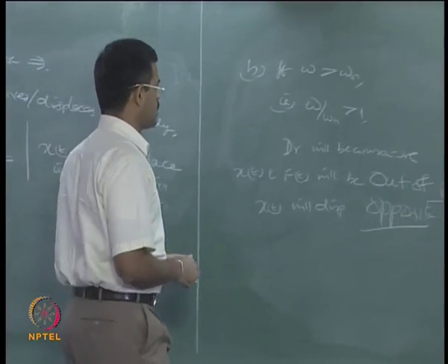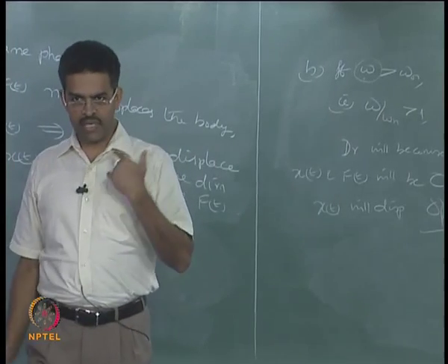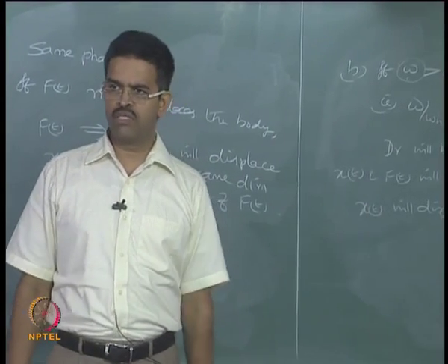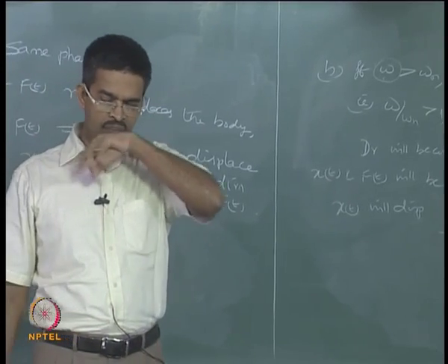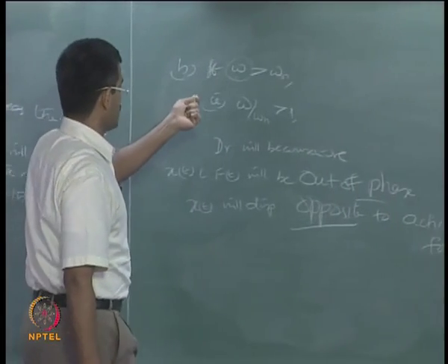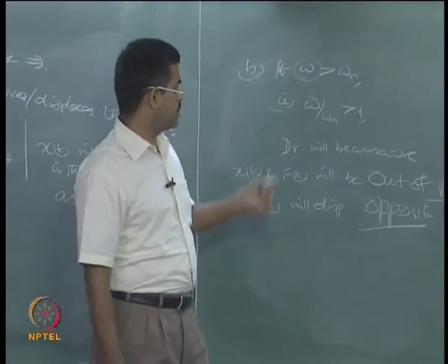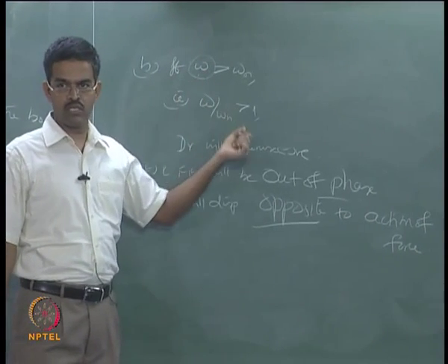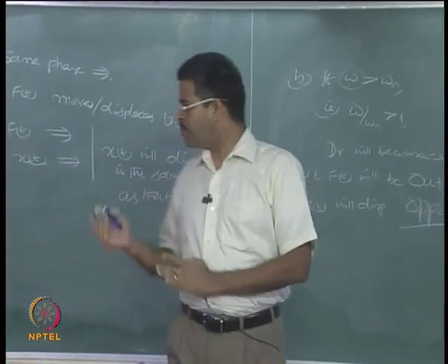Now, we all agree on what omega is and what omega n is. Omega is the frequency at which the force is acting on the system. Where do you get this frequency from? Wave loading has a specific frequency, we know it is a function of time. Wind load has specific frequency, we have already seen equations, etc. Right. So, these forcing function frequencies are known to us and they operate in a specific band, because waves do not encounter offshore structures at a specific frequency, is it not? There is a band. So, both the possibilities are there.